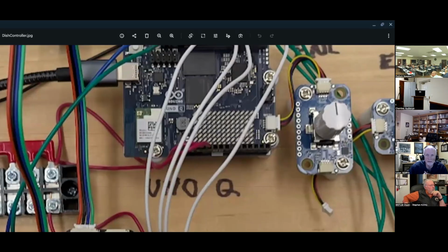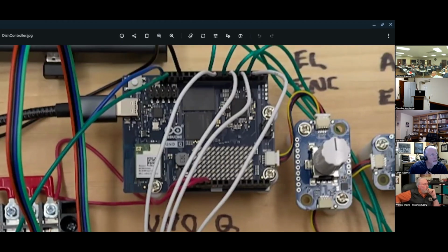If I'm going to zoom in a little bit here, some of you may have heard of the Arduino Uno Q. Which is a very interesting Arduino board in that it has a microcomputer on it that runs Debian Linux, as well as an Arduino supported chip, which gives you all the typical Arduino outputs. So not only can you handle, say, network traffic, but you can have a real-time operating system and write your code so it can react and stay on top of the movement of physical hardware.